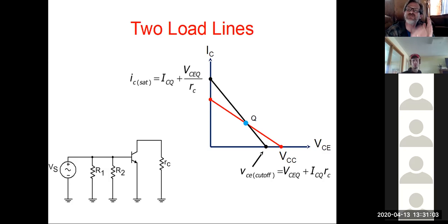So now we're looking at the DC and the AC optimally together and noting where those two cross over. That's our maximum range or our maximum point of efficiency for this particular transistor or circuit, if you will. So that would have set us up and we go, okay, this is our ideal Q point. So now we know what our ideal voltage ranges are and such. All right, go ahead and click the next slide.